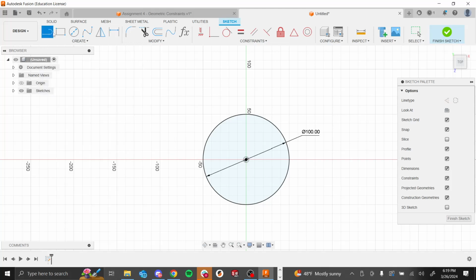Construction lines are really useful when you're creating things, especially when you pair them with different constraints. They allow you to hone down your geometry without adding complexity to your extrusion. You'll see what I mean in a little bit, but basically when you go to extrude or revolve things, Fusion is going to ignore the construction lines, but they're really useful for you when you make things.